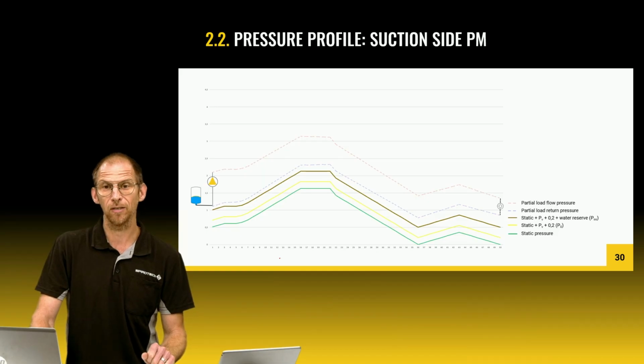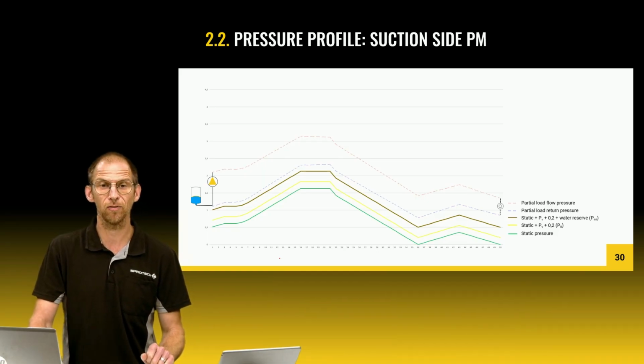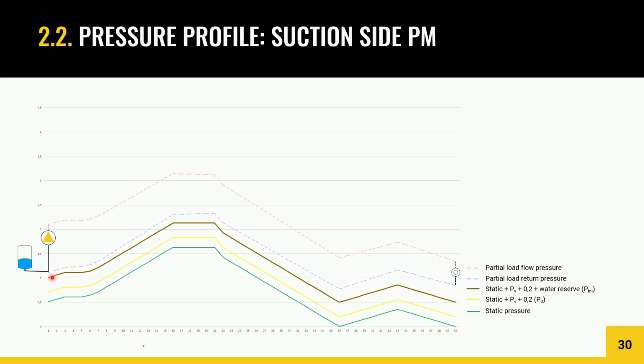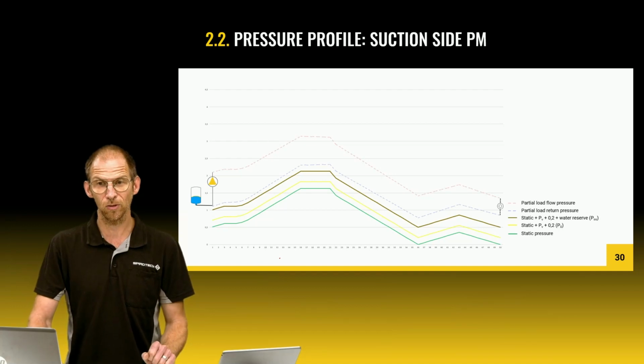Water is practically incompressible, and under steady operation, the mass flow rate entering via the supply equals the mass flow rate leaving via the return. So the same amount of water is coming back from the system through the pump as it is leaving from the pump. So there is no net accumulation of water in the circuit and no exchange with the expansion vessel in this state. Nothing that would change the set pressure. The pressure maintenance simply holds the reference point.